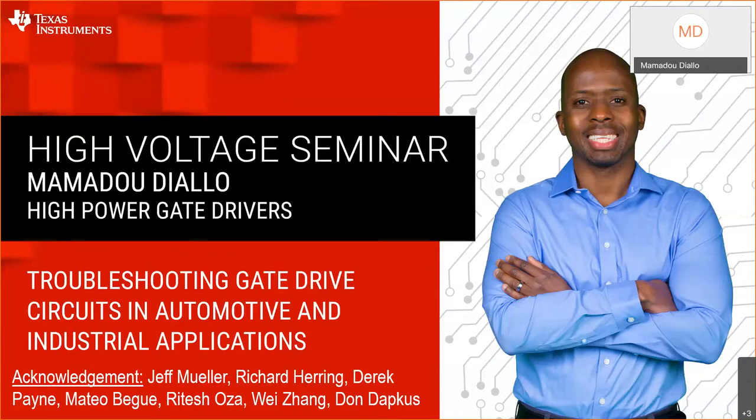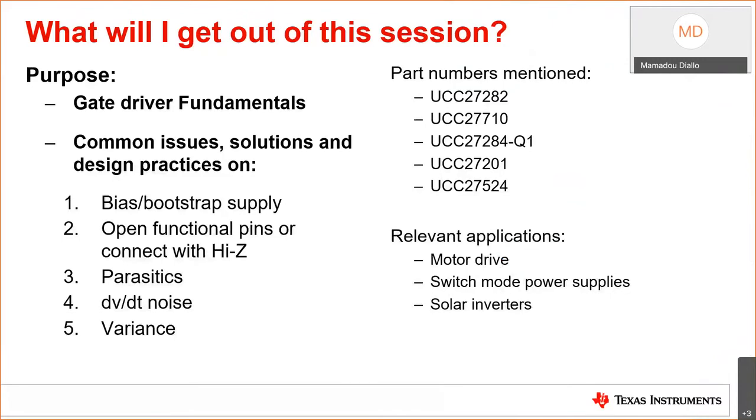Thank you, Tristan. Hello and welcome everyone. My name is Mamadou Diallo. I'm an application engineer with the High Power Drivers Group. This presentation will discuss pitfalls related to gate drive circuits in automotive and industrial applications, specifically gate driver biasing, bootstrap supply, and its components necessary to generate high side bias. I will also discuss the effect of open functional pins and the impact of DV/DT noise in gate drive circuit. I will then identify parasitics and finally show issues related to poor layout and how to correct them.